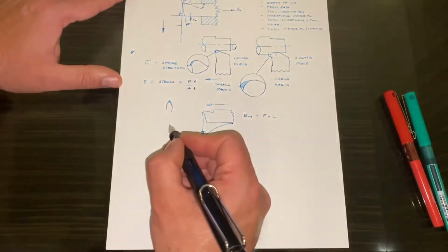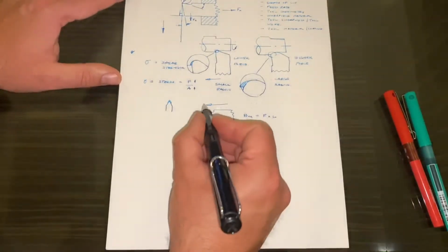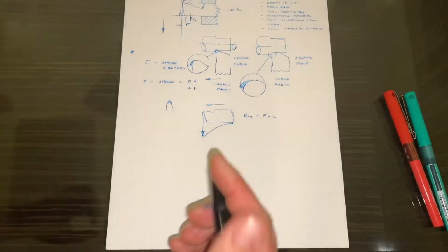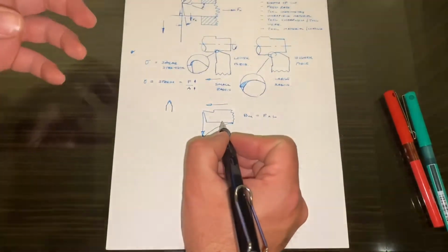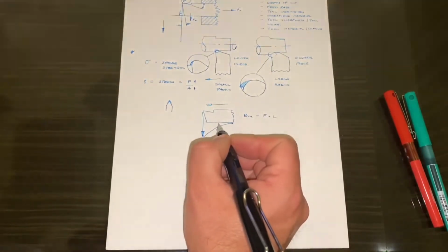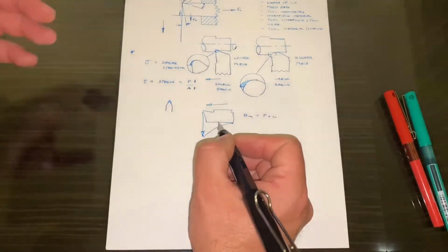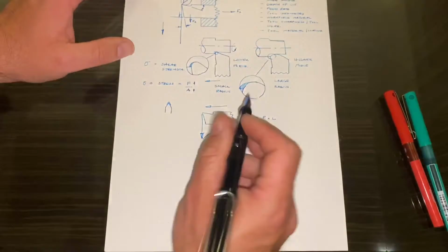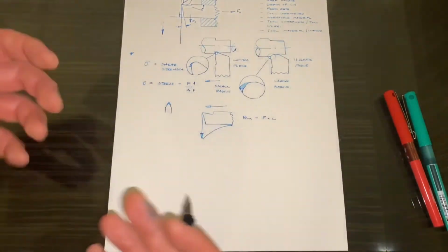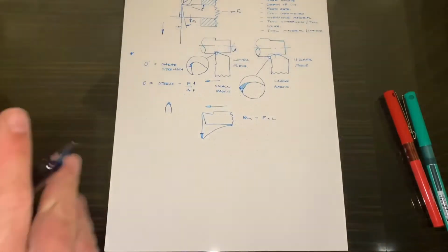The longer the tool and the higher the force, the greater the bending moment. The more that this tool has to overcome deflection. So why am I talking about deflection? The reason for it is that when we set tool height in a static situation, we are assuming zero deflection during the machining cycle.